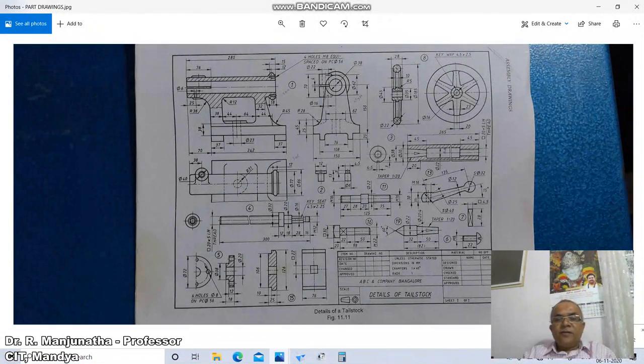To create this revolving center, we have a diameter 22 with a length of 32, and then we have 20.4 at this end. We don't know the diameter at the other end, but we have 50 mm length, and it has a taper of 1:20.